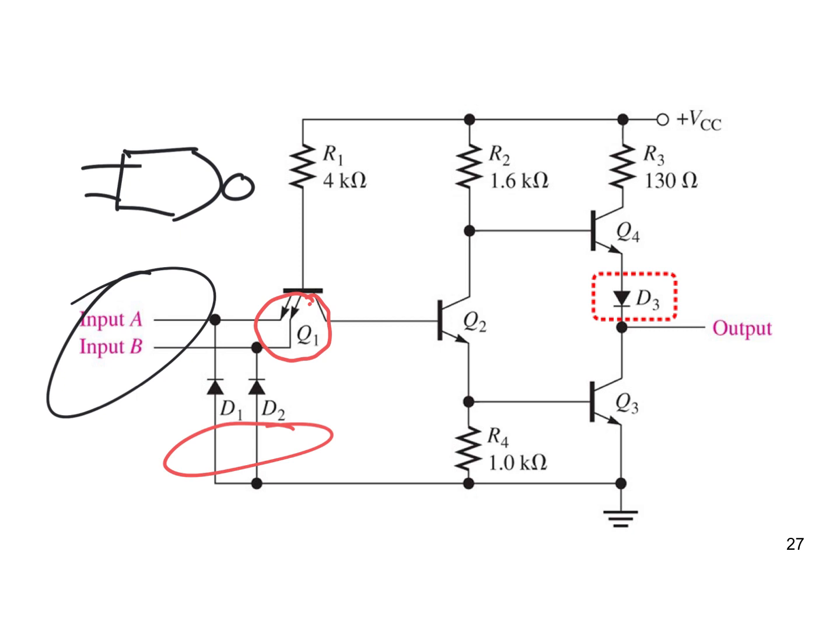Again, this D3 was there because the transistors could not turn on and off quickly, and is to prevent what were called switching spikes on the power supply rail. The internal structure here changes based on what the logic function is.